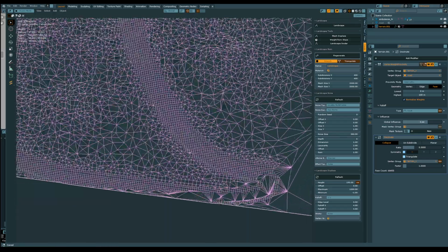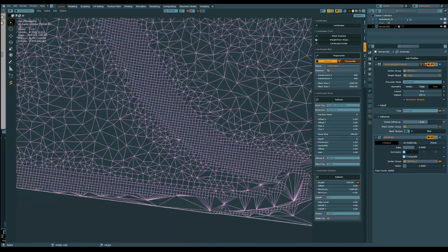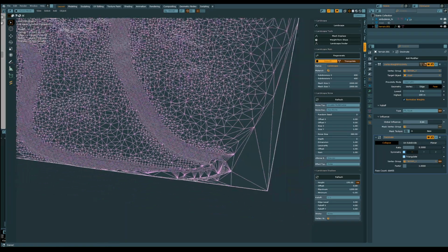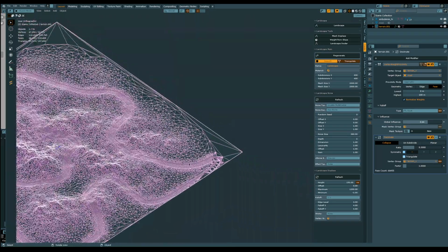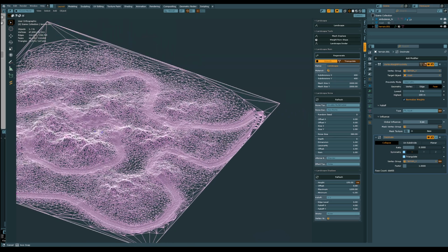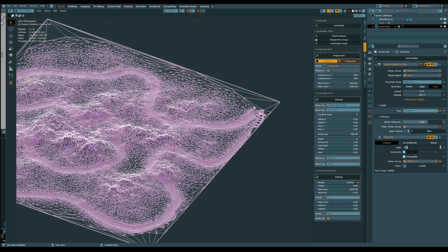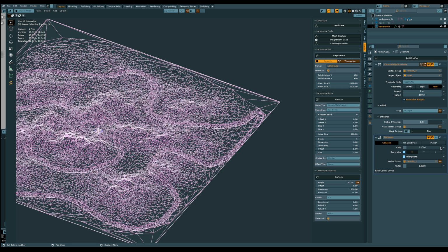But also, it kills in here. So yeah, don't draw your roads too close to the edge of whatever's supposed to be the terrain. You may get this kind of stuff. So from 0.3 we can put 0.1. That will reduce the poly count, the triangle count, even more.